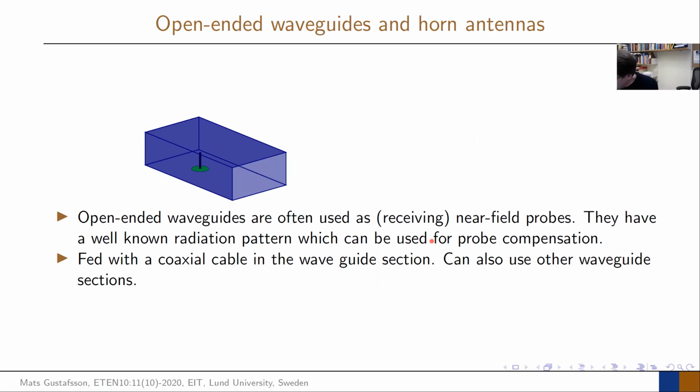And a typical case with this is that this structure here, if you would guess what is the size of this structure typically, it's typically lambda over 2. That's where you sit. Maybe it's slightly larger than lambda over 2. So between lambda over 2 and lambda in some ways. Again, it comes into these things that is where you have good determined solution to Maxwell's equation. This is what we call the lowest order mode in these cases. So you get something to radiate when this is of that order, lambda over 2 to lambda in some ways.